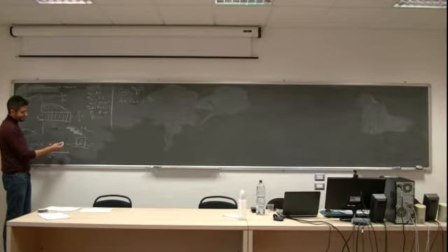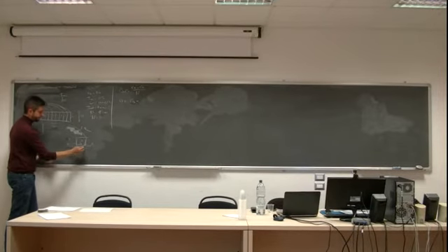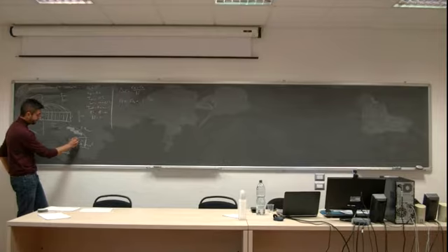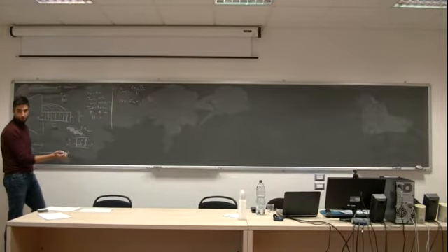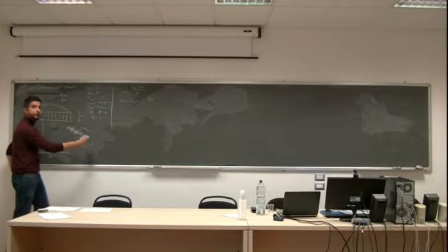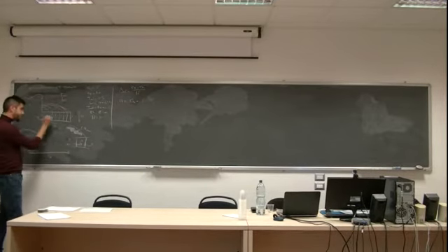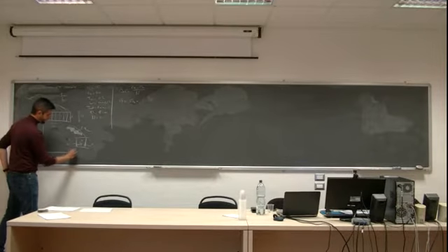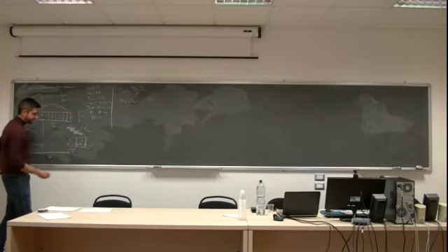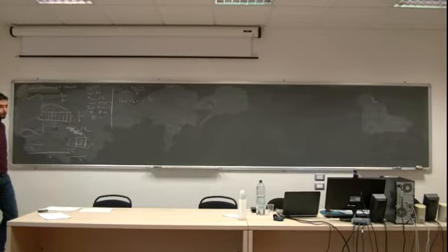Because it's in cylindrical coordinates, you have more area here than here. So you have to compute the area here and here to calculate the conduction coming from the west and the conduction going to the east. For that reason, I will need to know for each node the radius to the west wall and to the east wall of my node.